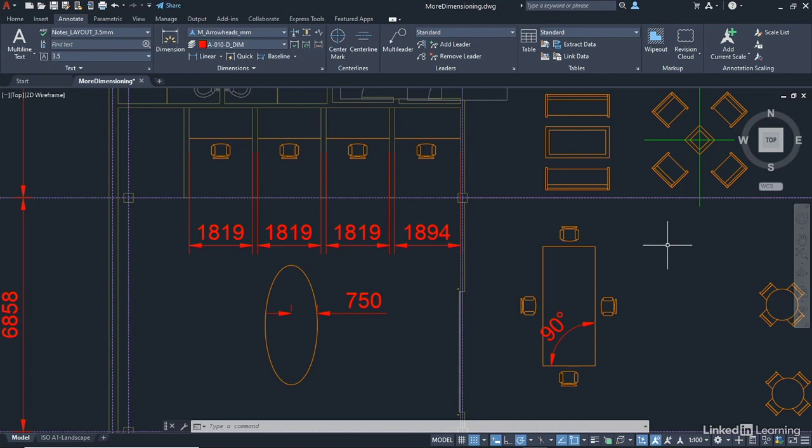It really makes your life a lot easier because it's just a case of click, click, click, rather than origin, origin, place dimension. Then repeat the dimension command that you need, which would be linear, and then origin, origin, and place dimension again. So use your automatic dimensioning. Make sure that your dim layer override is in place first, and you've got a much quicker way of going around and placing dimensions on your AutoCAD drawings.